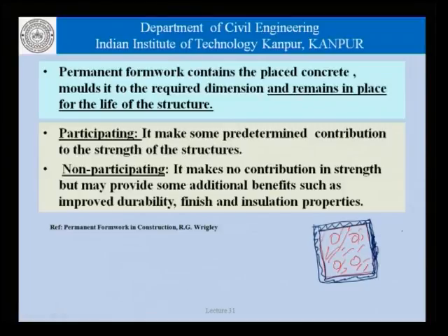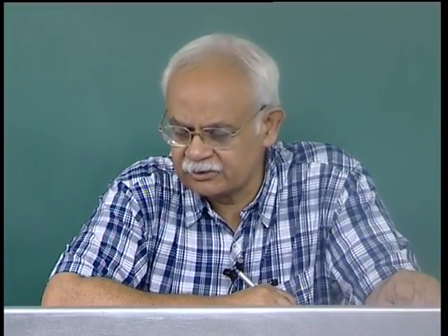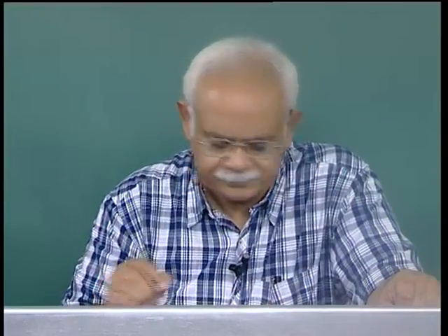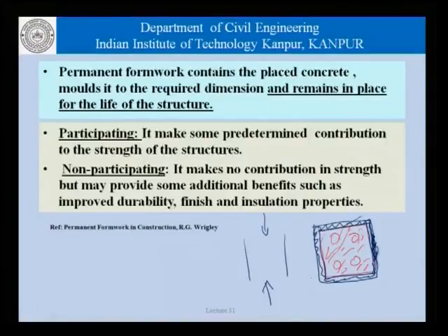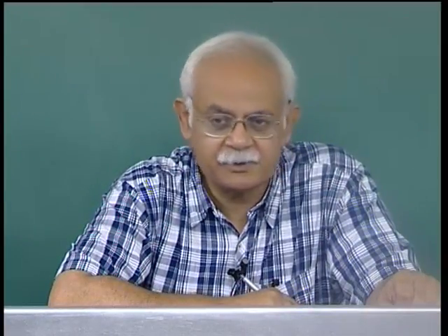we can expect two things. One is that this panel, depending on its thickness, the material, the kind of structural properties and so on, these panels are considered when we talk in terms of the load carrying action or the load bearing action of this column. The other possibility is that these panels are not considered when we are talking in terms of the load carrying mechanism of the column, and the same thing really holds for the beams as well. So, we have participating permanent formwork and non-participating permanent formwork.